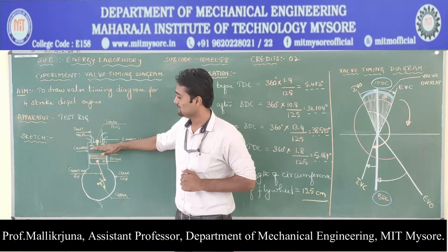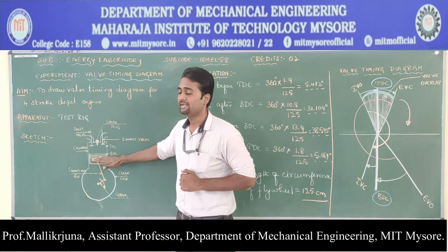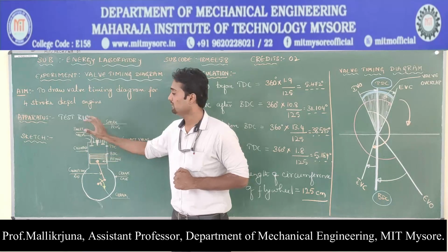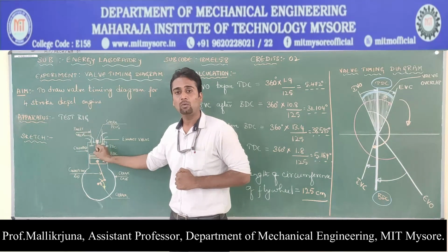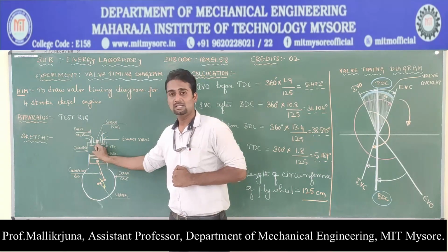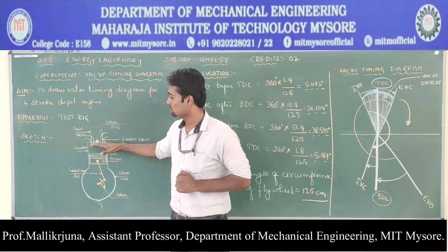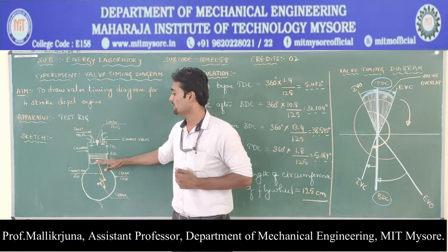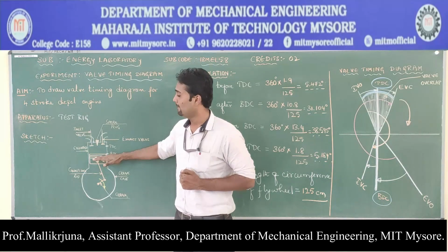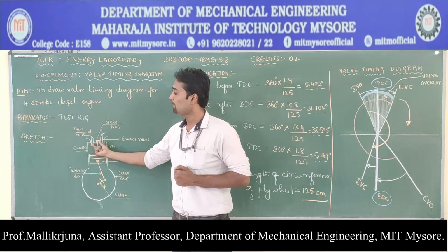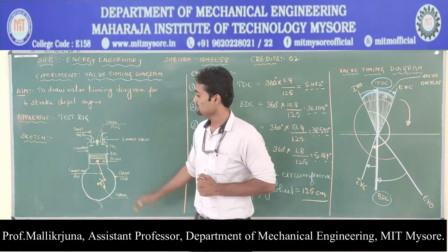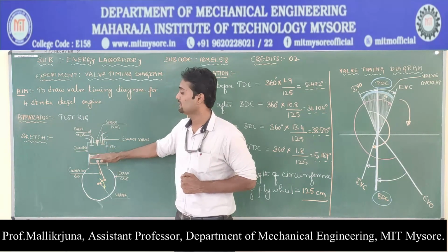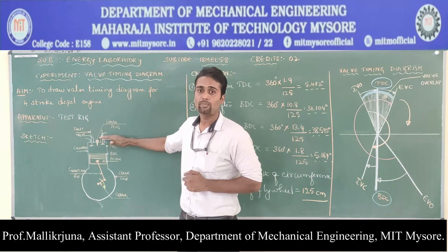That means the piston starts to move from TDC to BDC, during which if it is a diesel engine, only air enters into the cylinder. If it is a petrol engine, charge, petrol as well as air enters into the cylinder. So during the suction stroke, piston moves from TDC to BDC. Once suction stroke ends, we will be moving on to the compression stroke, during which piston moves from BDC to TDC. During that time, both the valves are closed. That means mixture which is present over here or the air which is present over here will get compressed during the compression stroke. That is the second stroke.